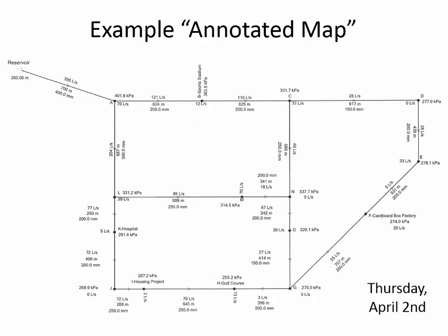240, I think. 240. So the closer this student gets to 240, the happier I am. That's evidence of optimization. If I look around and the pressures are in the 400s and the 500s, I start to say, oh, this student didn't make the pipe small enough. You could have made that pipe a little smaller, and it would have reduced the pressure a little bit, but it wouldn't have taken the pressure down below the limit. And so that pipe is unnecessarily large. Shame on you, student. Right?